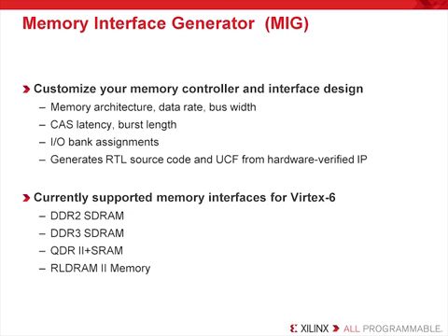Currently, the MIG supports DDR2, DDR3, QDR2, and RLDRAM2 memory controllers for the Virtex 6 device family. Note that different controllers are supported for different device families depending on the ability of the device to meet the typical performance required of the memory standard. However, it is often the case that as a new device is introduced, it takes a little time for all the possible supported memory controllers to be supported for that device within the MIG. So just be sure you update your MIG utility periodically to get the latest cores, or call the hotline if you might need another controller that's not shown within MIG.